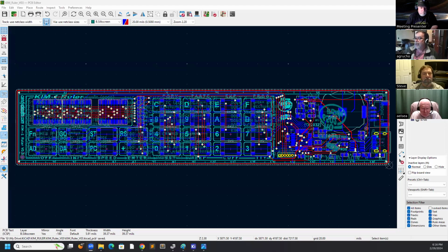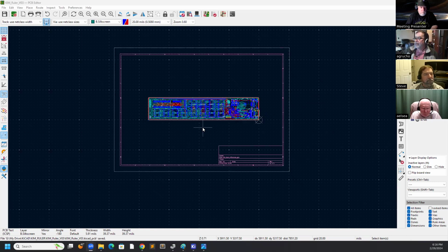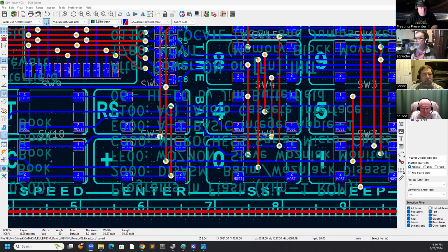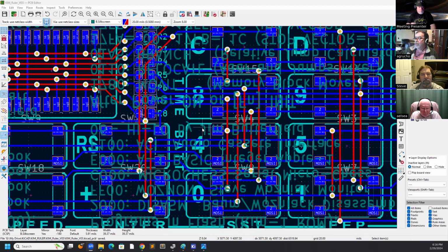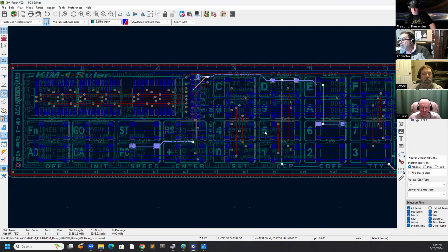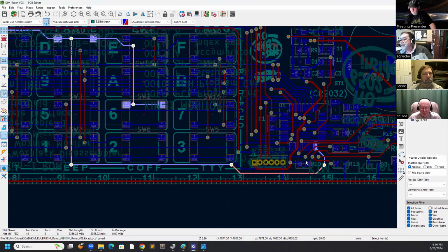You see, this is the editor. You do the schematic, and there is a rule checking, a netlist check, to be sure that you have all the connections done. You can press any point and see all the connected parts. This is the microcontroller.